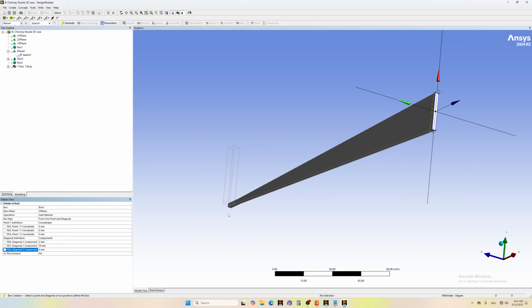And again, now let's put it exactly in the middle. So that's why initially we put the coordinates exactly in the middle of the drawing. It's easier after that to draw the rest of the geometry. So here on Y, let's move it -15. So you see now how it moved.